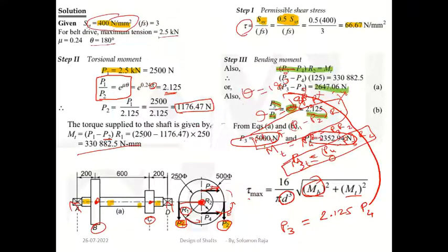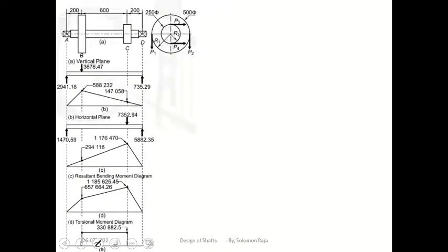Now we will move to the next slide. There we are going to find the MB value. To find the MB value, we have to draw the shear force diagram and bending moment diagram for the shaft. No need to draw the shear force diagram. We have to draw the bending moment diagram for the shaft, to find the bending moment value.